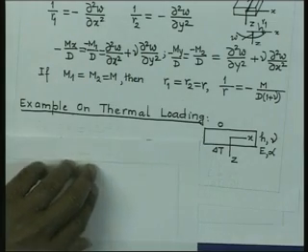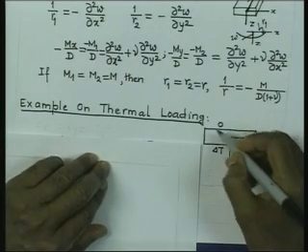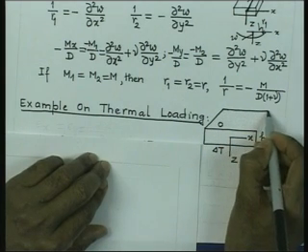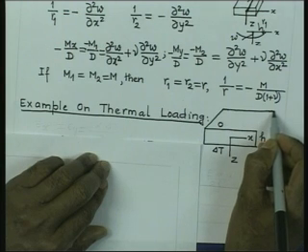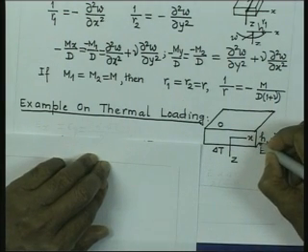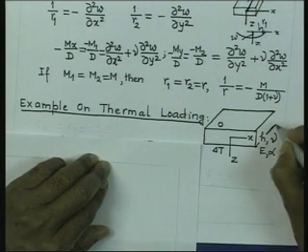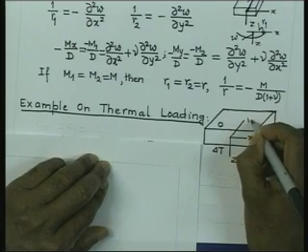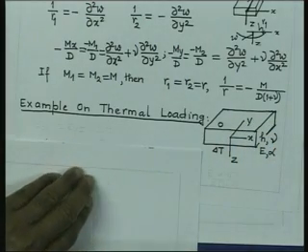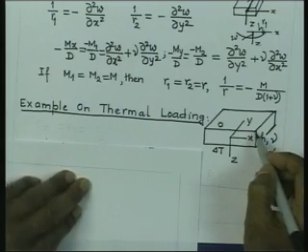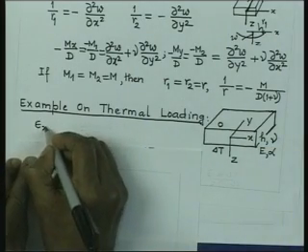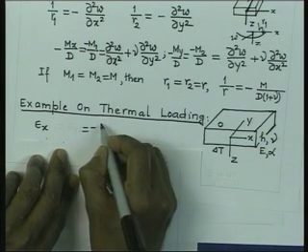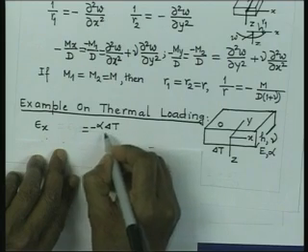Now, if I do this, then the plate will undergo strain in both the directions without any distortion. So, if you consider that this is the plate and this is your y direction, then we are going to get the strain here at the top, let us say in the x direction, and that is going to be nothing but minus alpha delta T by 2.